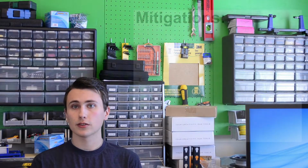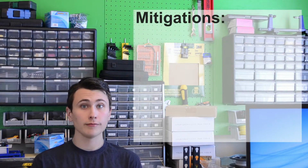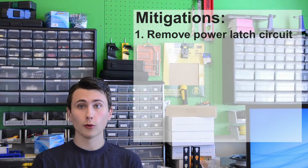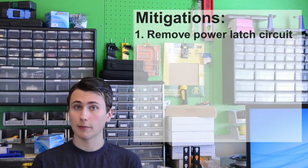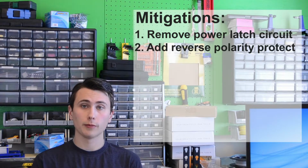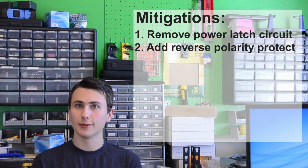Once the root cause of this issue was discovered, the mitigations were obvious. 1. Remove the power latch circuitry, since we couldn't use it anyways. 2. Use the board space freed up by removing that power latch circuitry to add reverse polarity protection with a PMOS FET. That way, we won't need a third revision of the PCB if someone plugs in a barrel jack with the wrong polarity.